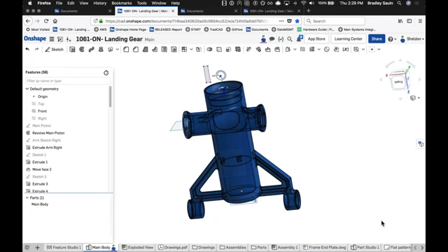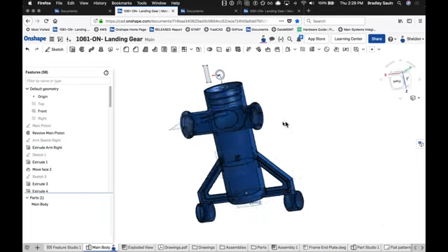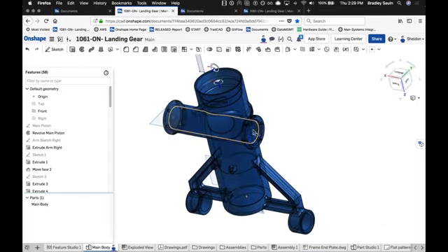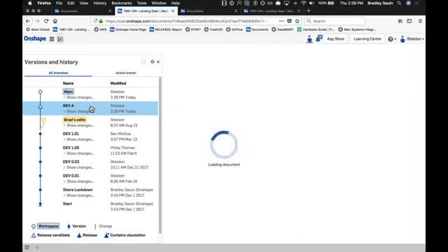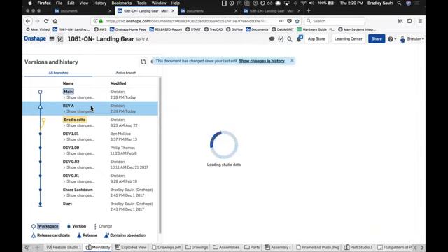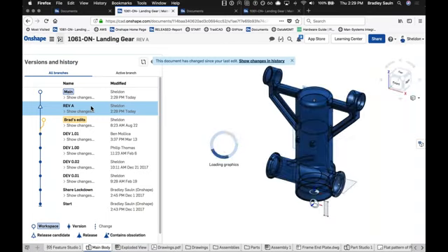For those of you that are new to Onshape, looking at this for the first time, even though I have a current pending release, I can still actively edit and modify the part that's pending. Because of how our timeline works and how we track data, that previous point in time is still locked down. So this point is still uneditable as it's pending.